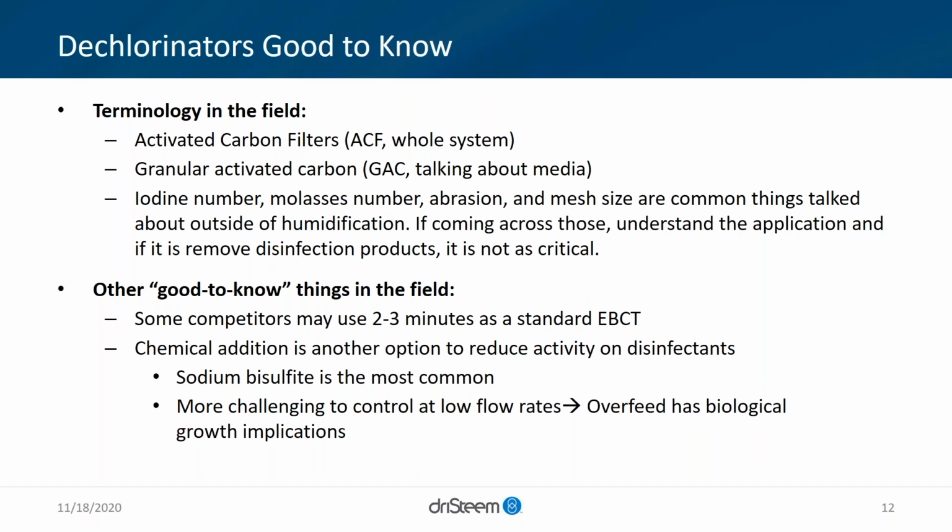Some other good things to know: if you see upstream of an RO system a chemical feed, it could potentially be a chemical feed to remove the disinfectant. What I like to talk about there is if you see that, essentially a magnitude of things can happen. You could lose power, number one, which your RO wouldn't work anyway, or you could run out of chemistry. You could have the wrong feed rate on your chemistry.